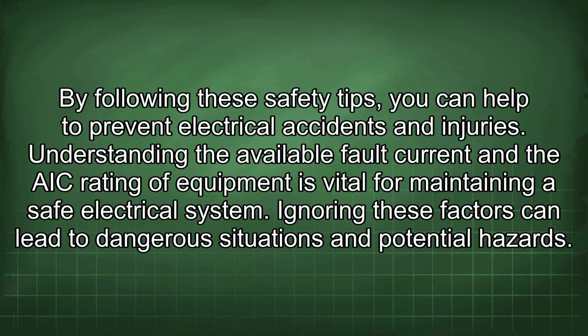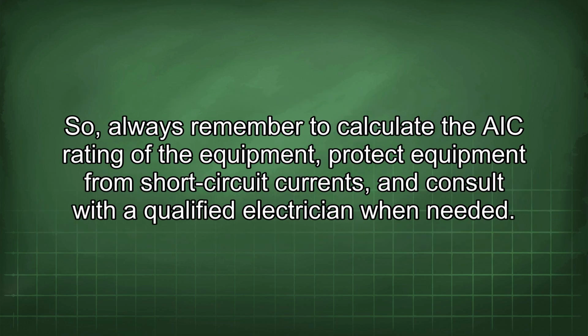Understanding the available fault current and the AIC rating of equipment is vital for maintaining a safe electrical system. Ignoring these factors can lead to dangerous situations and potential hazards. So, always remember to calculate the AIC rating of the equipment, protect equipment from short-circuit currents, and consult with a qualified electrician when needed.